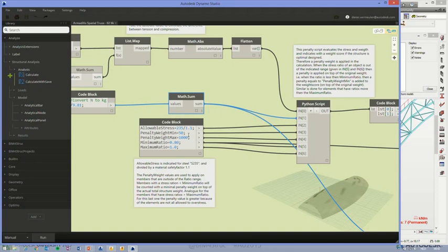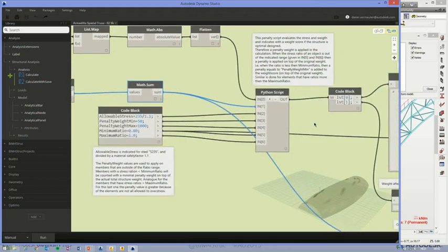Okay. Is the truss width working? Can test it again. So now I'm doing some kind of manual operation on it. And what it has done in here is something special. It has generated 3 models. If I look into my browser in here, which is Armadillo, it's manual optimization. Let's take these ones. You see, I changed the values 3 times, so I get 3 models. Afterwards, you can reopen those models and have a look at what happened if I change the truss height, if I change the truss width, and you can use that for further evaluation of your design.